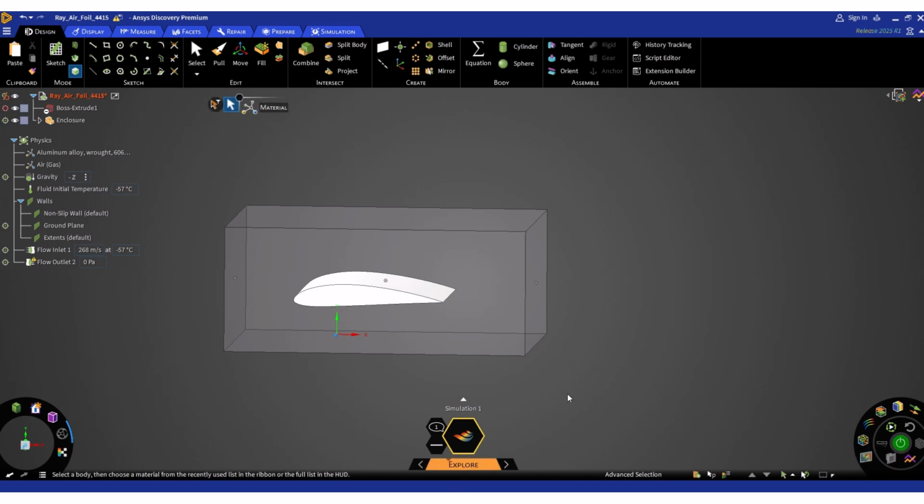Oh, before we do that, the explorer option over here, or the fidelity, is the level scale where we can define how long and how good a simulation you want. I always like to keep it at about half or less than half, so that it doesn't apply excessive load on my graphics card. And now we're going to go and click on the solve button.